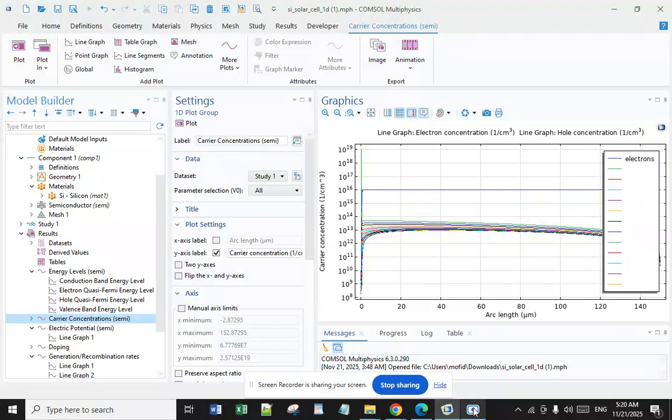The absorber material is typically a doped p-type square wafer having a thickness of around 300 micrometers and an area of 10 multiplied by 10 centimeter square, or 12.5 multiplied by 12.5 centimeter square. On both sides of the crystalline silicon wafer, a highly doped layer is formed: n-plus type on the front side, and p-plus type on the back side respectively.